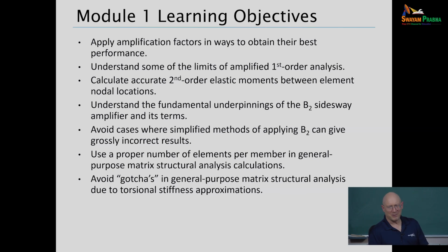Consteel basically surmounts all that because everything they do is based on a 14 degree of freedom element with 3 translations, 3 rotations, and a warping degree of freedom at each node. That allows us, with thin-walled open sections, to capture the thin-walled open section beam theory behavior quite well, and that's the basis of our code provisions for a lot of the things we do.